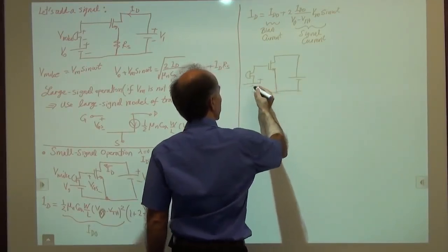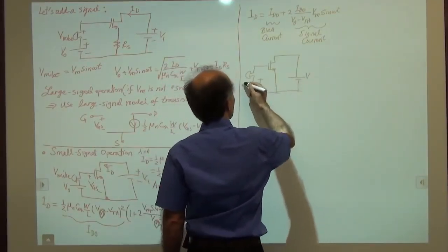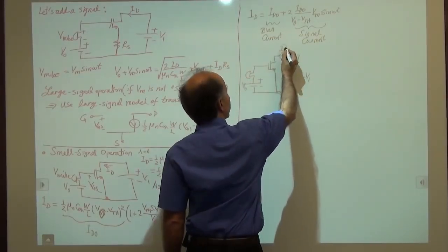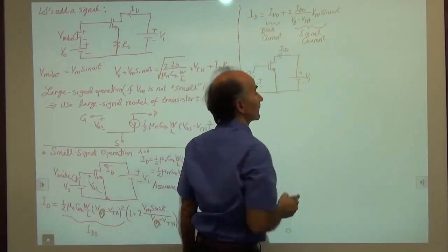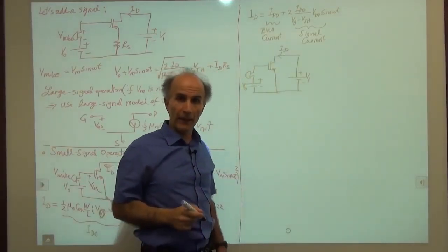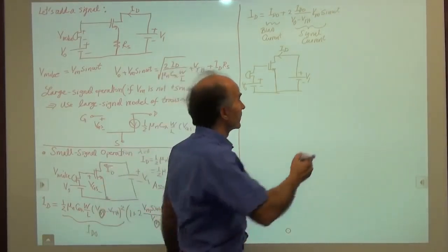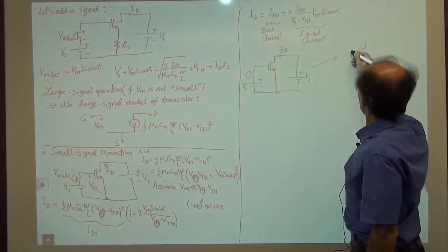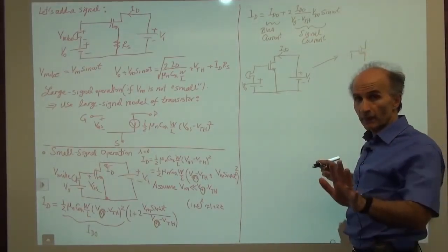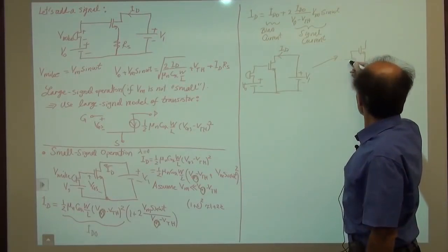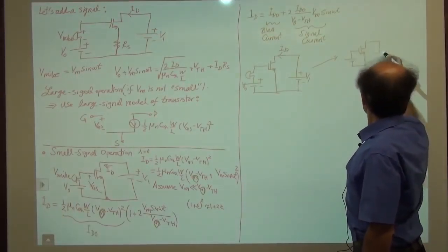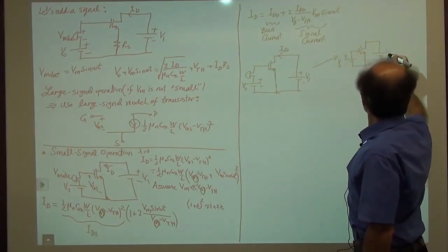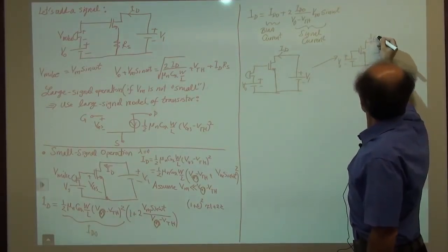And what we see is that when I'm talking to the microphone, V0, V1, then I get this total ID here, right? So I'm thinking maybe I can decompose this into two. Here's one. I have a MOS device with no signal coming in, just the bias quantities. So here's the MOS device with just the bias quantities. So we have V0, V1, a certain current, ID0.